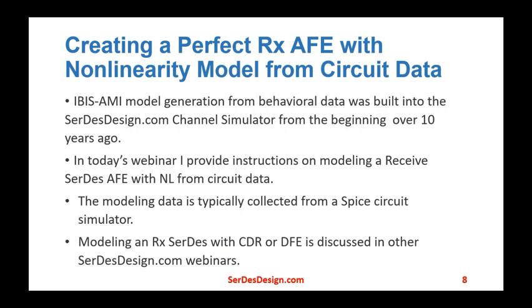Creating a perfect receiver AFE with nonlinearity model from circuit data. The IBIS-AMI model generation from behavioral data was built into the SerDesDesign.com channel simulator from the beginning. I have used this process over the past 10 plus years, providing custom IBIS-AMI models to over 40 plus companies based on the circuit data they provide me.